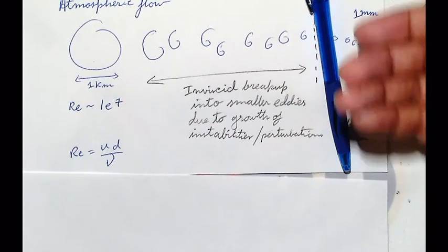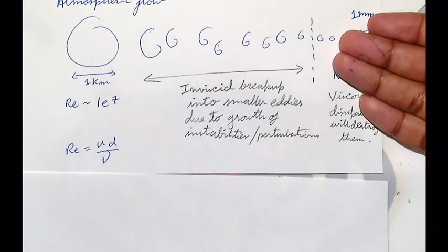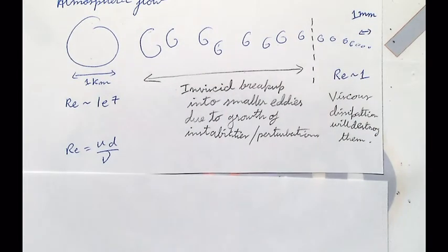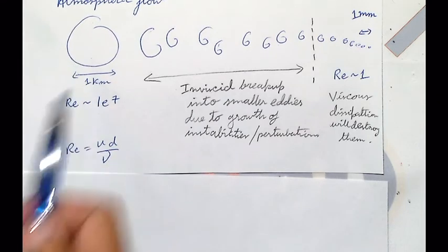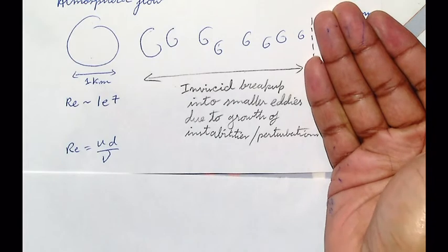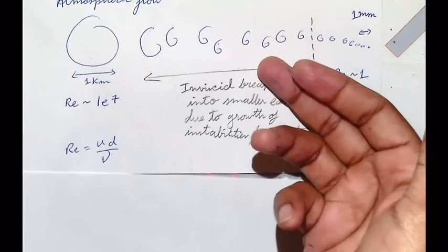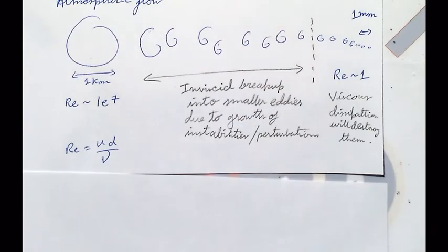Okay? And what will happen to your simulation if you don't resolve the dissipating scales? To just continue to add energy. Yeah, you keep pumping in energy at the large scales. There's nothing that dissipates. What we talked about right now, right? Eventually, all the energy will pile up at these eddies, and the simulation will go unstable.